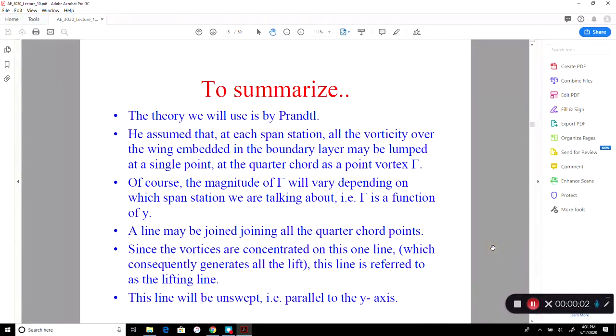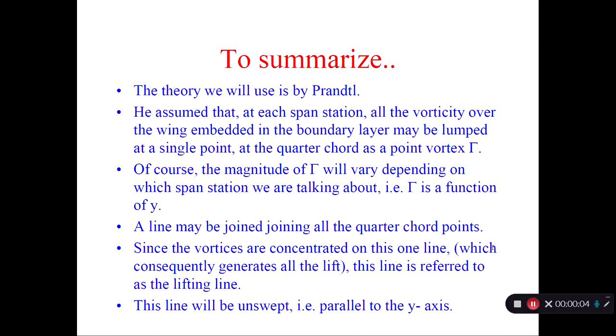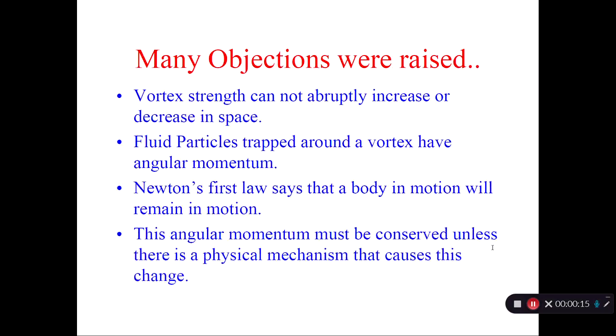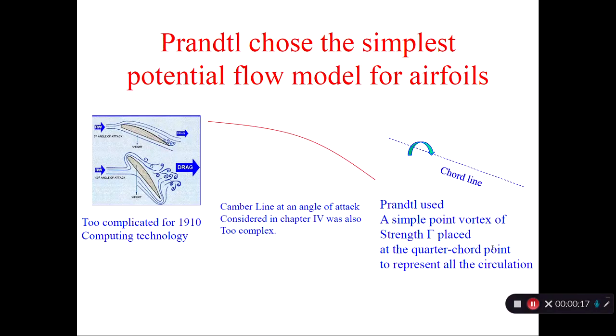We will resume our discussion of Prandtl's lifting line theory. This is the slide that we left off with. As I mentioned, we are going to deal with Prandtl's model. He assumed that at every span location, there's just a single vortex at the quarter chord.